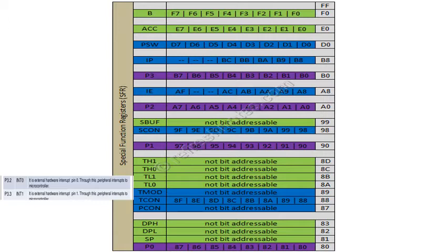high priority. To alert the microcontroller, peripheral devices can use either an edge-triggered interrupt or a low-level signal which triggers the interrupt. IT1 and IT0 are used to select which kind of signal will be used to interrupt the operation of the microcontroller. If IT1 is set to 1, then a falling edge signal will be seen as an interrupt, whereas if it is 0, a low-level signal for a certain duration will be used to interrupt the microcontroller.